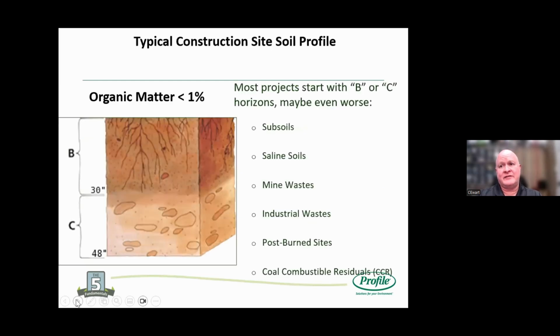So typical construction site, this is what we see as our horizon. That top 12 inches is gone. One of the first things they do in a residential development or even highway construction is they often will pull that topsoil off. Typically in construction, we don't want to have that topsoil in place because it's compactable. It doesn't hold up very well. If we've got heavy buildings or roads or whatever going on top of it, we typically want to get back to that subsoil. We've got good, hard, compacted soil that we can put whatever structure on top.